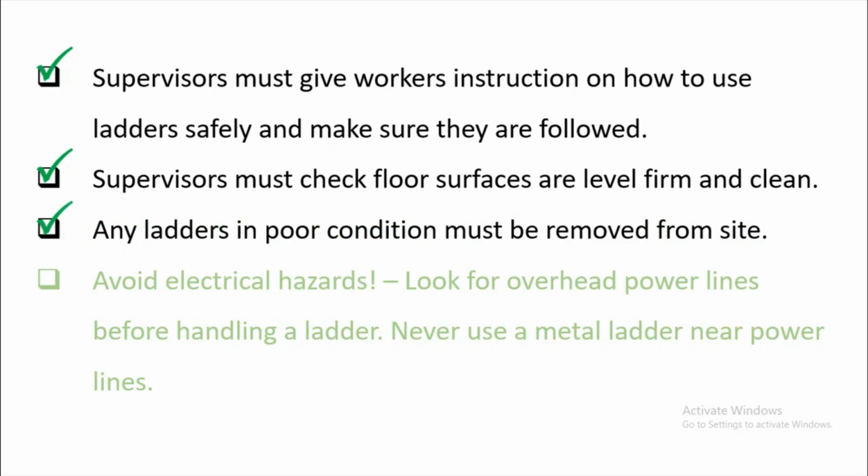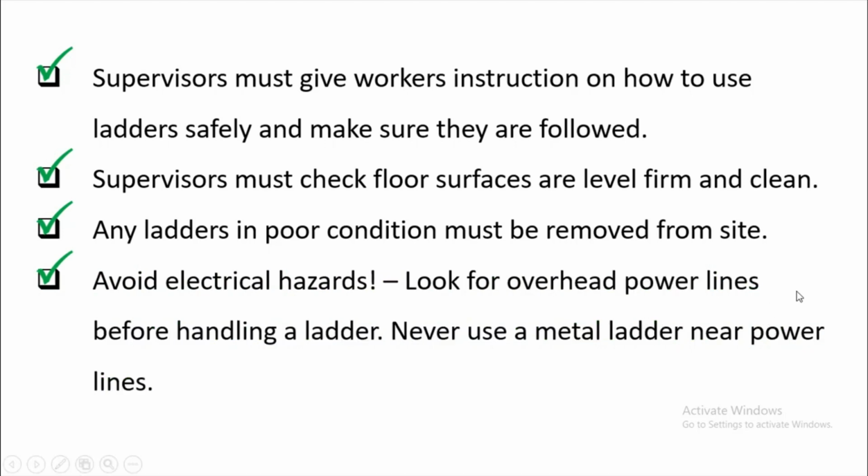Any ladders in poor condition must be removed from site. As I said a while ago, if you find that your ladder is in bad or poor condition, tag it unsafe to use, and remove it from service. Avoid electrical hazards. Look for overhead power lines before handling a ladder. Never use a metal ladder near power lines.